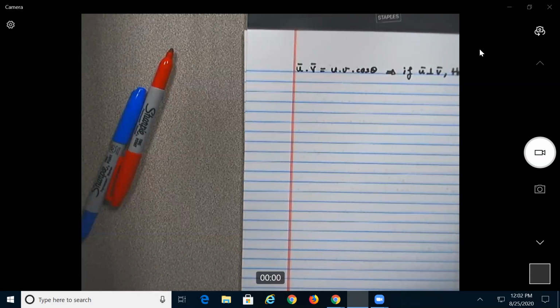If you had a force and you wanted to find the magnitude of that force in one direction, you would take the vector of the force and do the dot product with the vector giving the direction you wanted to choose. So the second function of the dot product is to find the component of a vector in a certain direction. In statics, that was called for the forces.